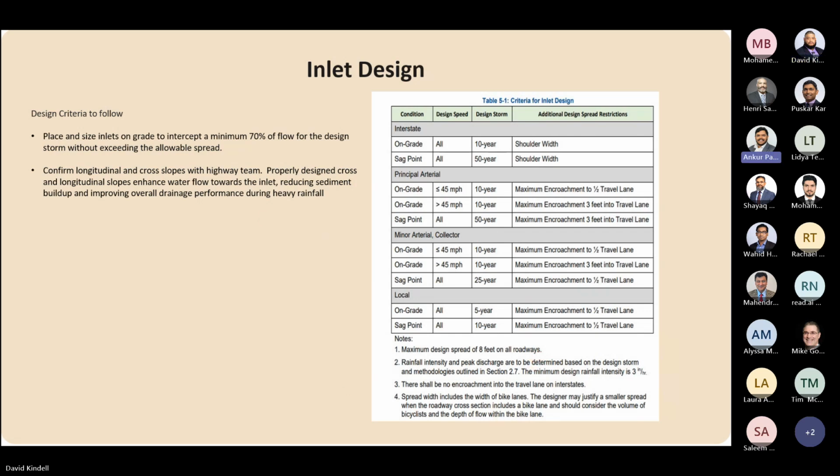Yeah, so this is the specific criteria that has caused a lot of issues for our drainage design and scoping, this manual, as David mentioned. This manual was published by MDOT in 2023. I think basically all new projects, in general the criteria is if your PI was after January 2024, then you have to follow these rules. This criteria is a lot more strict than the previous one.